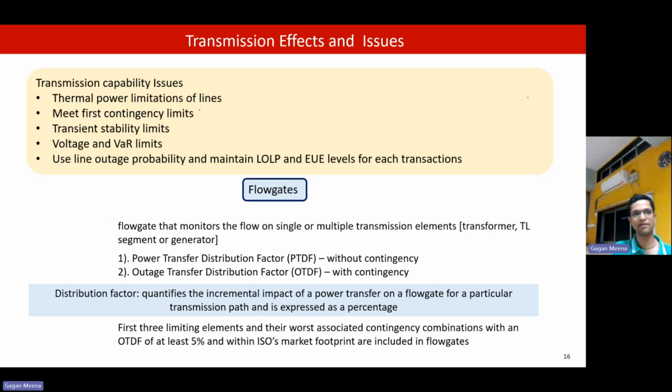And because of the thermal limit, we cannot. There is a limit to the reactive power which can be carried by the transmission line. And when there is an outage, based upon the line outage, every utility or system has to maintain reliability. These are reliability metrics, measures to ensure that the system will be reliable under these outages or any kind of emergency situation.